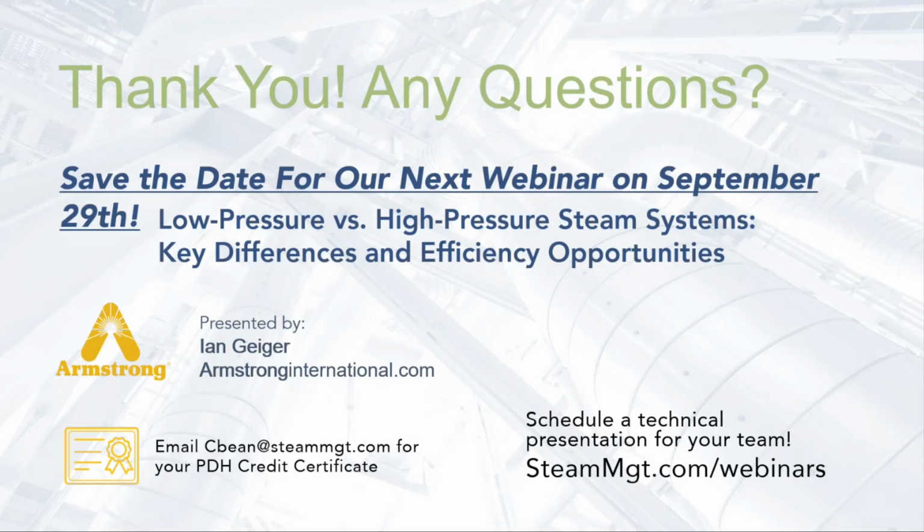I wouldn't say it's commonly done, but it is something that you could do. It's actually a very interesting concept. In that installation image that we did show you, you could put it upstream of another manufacturer's trap if it's below 15 psi, and you want to know if it's flooding and backing up. That would be the way that you could measure. However, it's not usually able to catch blow through traps in that specific type of application. You would only be catching the trap if it was flooding.